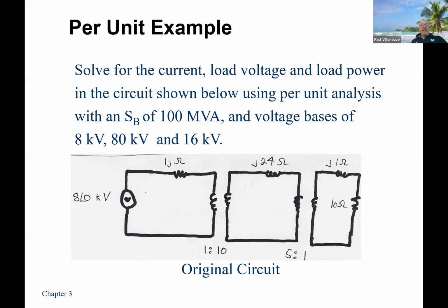All right. Take a look at an example. We have a very simple single phase system here. We have a single phase generator cranking out 8 kV, and we're going to pick it to be the reference, at an angle of 0. Its internal impedance, or the transformer impedance, you can take your pick, we'll call it transformer impedance, the equivalent is 1 ohm inductive. Then we're going to step up our 8 kV line to a nominal 80 kV line. Then our transmission line is j24.